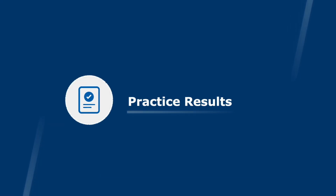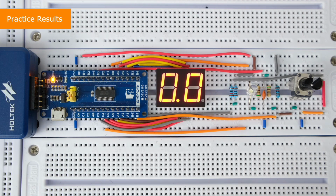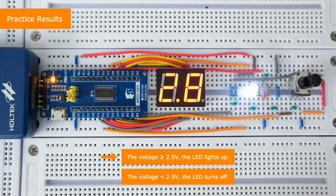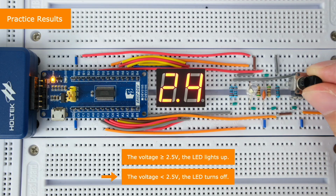Practice results. After the MCU is powered on, the digital tube displays 0, indicating that the current positive input voltage is 0 volt. We can observe that the LED lights up when the voltage is greater than or equal to 2.5 volts. Conversely, the LED turns off when the voltage is less than 2.5 volts.